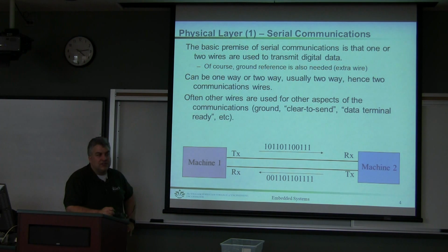There are some devices, like the ping you just saw, didn't that have a very rudimentary form of data communications, right? A single bit, so to speak. A rising edge of a pulse from your microcontroller application to the ping sensor, and then the ping responds with a single pulse. That is a very simple form of serial communications. Same wire.